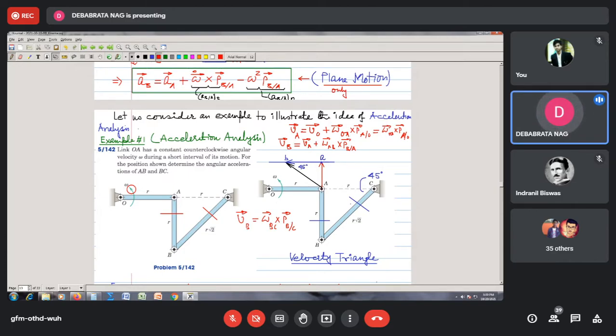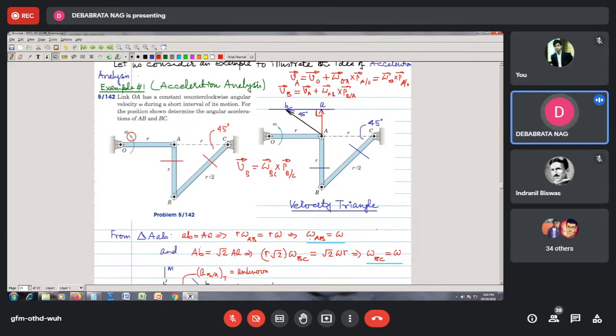So therefore, through point A, I draw a line parallel to this blue line, or perpendicular to this line BC, and allow this black line that I have drawn to intersect the previously drawn blue line at point small b. So my velocity triangle is complete, for which you see this angle is going to be 90 degrees. Correct? So our triangle is a right angled triangle. Now from the geometry I note that this angle is 45 degrees. So therefore obviously this black vector is going to be 45 degrees. So it means that this is an isosceles triangle. So from this triangle, I say that AB will be equal to AA.